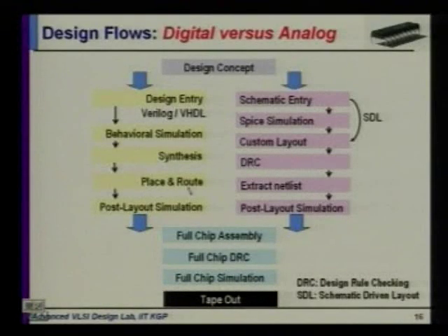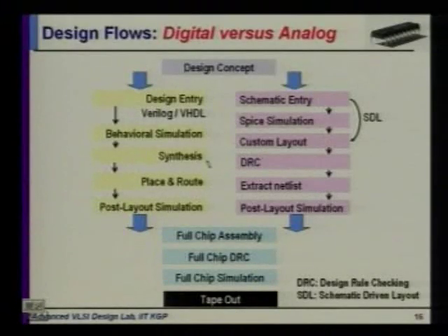So in spite of all the synthesis and all the timing optimization, if you go wrong in this step, then you will see that finally the chip is not able to meet your timing requirements. And what would that mean? That you planned for a 4 gigahertz processor and you end up with a 30 megahertz processor, right, because you are not able to run it at a higher speed. That's bad news. So these steps that you see here are not unrelated.